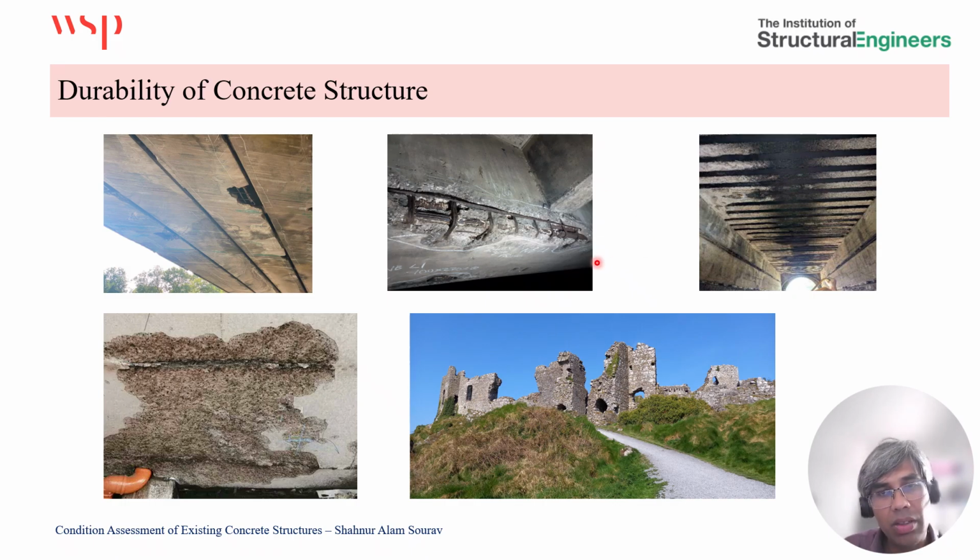The middle picture on the top shows the concrete spalling with exposed reinforcement as well as exposed duct and tendons. I should say this is a post-tensioned beam, so these ducts and tendons are crucial to the overall capacity of the structure. In this case, they have already been exposed, where the duct and tendons had significant section loss and fractures in certain locations.